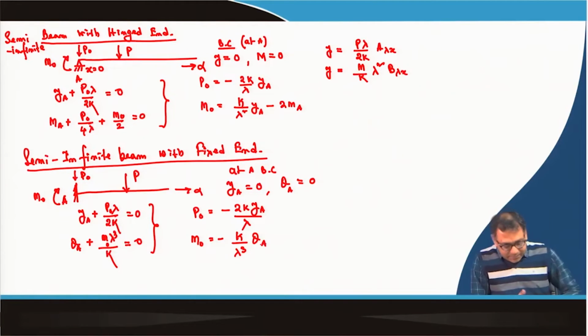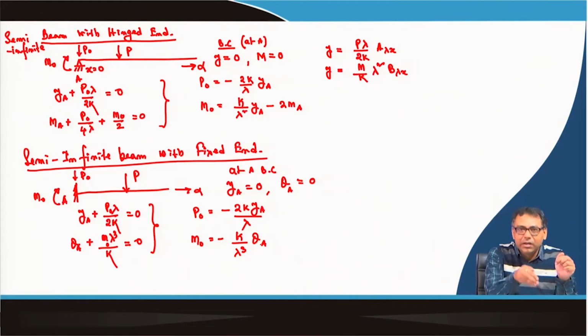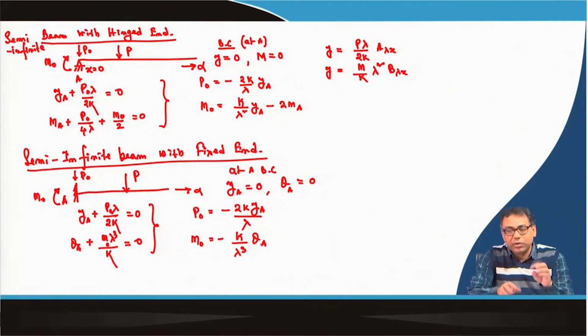And remember that it depends upon whether the point or your end condition is left side to the moment or right side to the moment, or the concentrated load, or any loading condition, because I have discussed the 3 loading conditions, and during the derivations I have given only the concentrated load. It is not true that only concentrated load will act. No, there can be a UDL also, there can be a concentrated moment also.